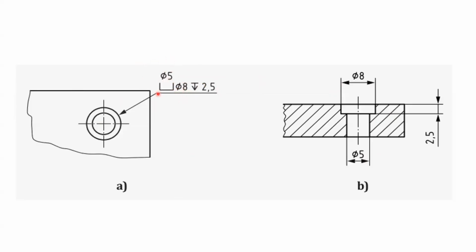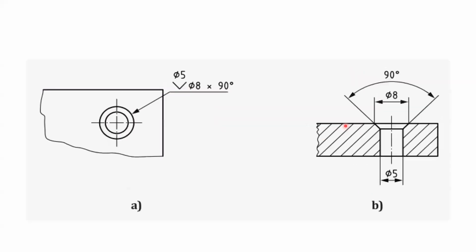So what you do is on the top line you specify this base diameter, and on the second line you insert this symbol and add the top diameter and the depth of the cut. This is the symbol to indicate the depth of cut. If you have a V-shaped one, like here, where countersunk bolts and rivets are used, then it is a similar thing. This angle symbol indicates this is the angular countersunk hole.